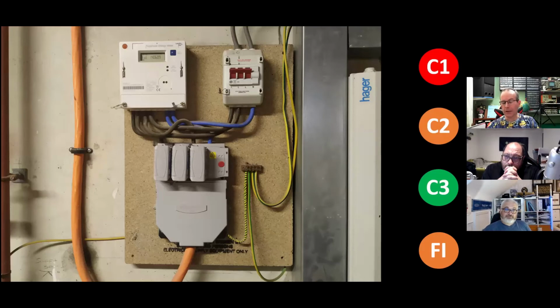So what the DNO has actually done is where it comes into the main distribution cupboard, which is one of those things with the J-type fuses in it, they've basically linked the red phase that comes into 2 of those and the blue phase to the remaining one, and there is no yellow phase on the old colours. It just doesn't exist. So it was all set up for 3-phase when it was built, but they've got basically 2 phases to use, and that's your lot.